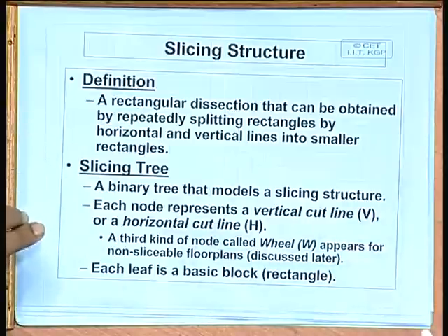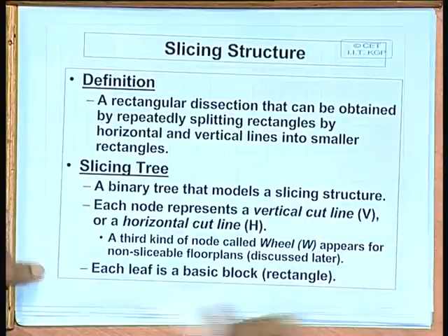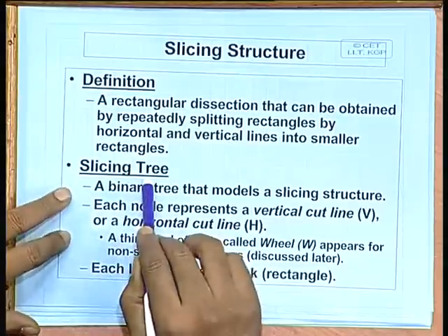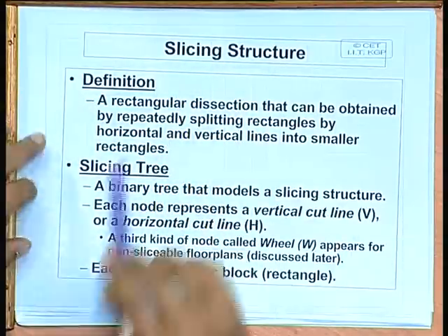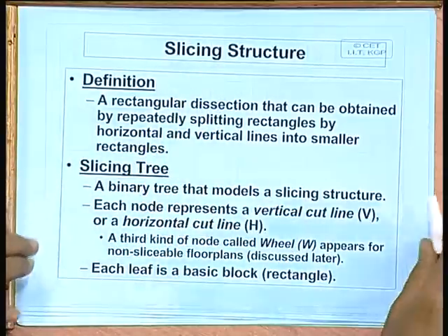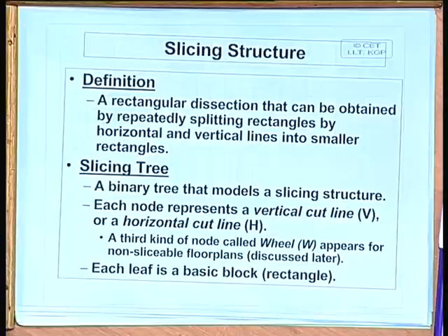Okay. So, fine. Before going into the algorithms, we talk about some of the data structures that we typically use to represent a floor plan. One such data structure is called a slicing tree, which is based on the so called slicing structure. Slice, as the name implies, means I just cut something into two pieces, and a slice I can make either horizontally or vertically.